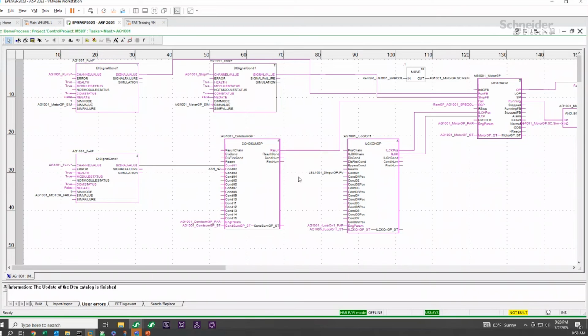And so if I have a VFD on a variable speed motor, I can link those two so that logic would show up here together. The VFD control and the motor control would all be present in the same section of logic and automatically linked together. But we defined that we had some discrete inputs, discrete outputs. So we've got a run and stop discrete inputs. We have a failure condition input. Could be just the overload condition that's in here. And we have other failure conditions that we've defined. So there's a high level switch, for example, on that vessel that comes in as a failure condition as well.